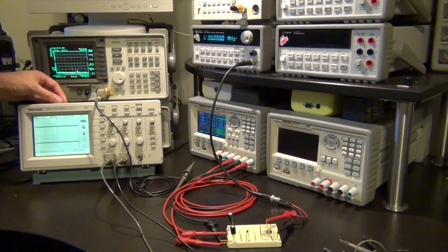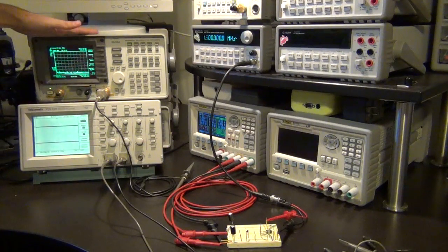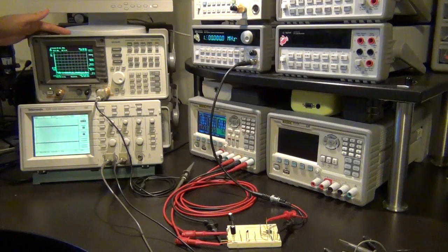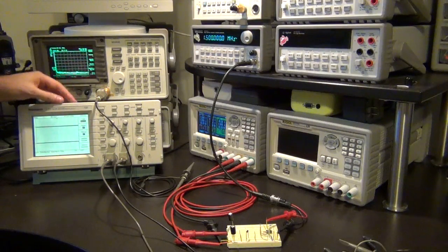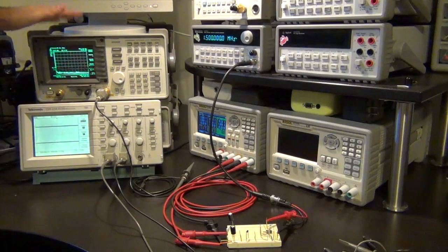But the main reason is that the dynamic range you get from an oscilloscope when you perform spectral calculation is nothing that even comes close to the dynamic range you can get from a spectrum analyzer. This is because this is mathematically computed using a low resolution A to D converter, whereas this guy has a very high resolution A to D converter and actually down converts chunks of frequency and gives you a very high dynamic range. So nothing can beat a good spectrum analyzer when it comes to spectral information. So I'm going to use this guy to look at the spectrum.